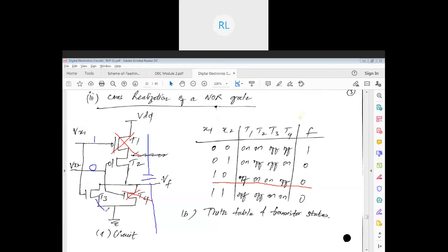Now I have the values here, and I have my 1 here, which means T3 is conducting. Since T3 is conducting, and as I told you, I have a capacitor connected across my output. Since T3 is here, it can discharge the capacitor to ground. Since it is discharging to ground, I should get 0 value. So are we getting that 0 value here?